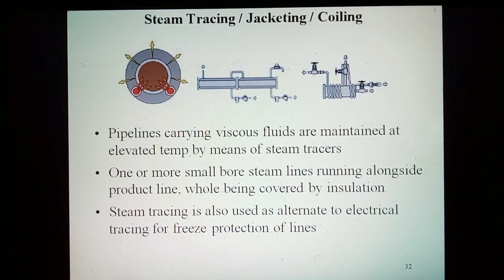Steam tracing. Pipelines carrying viscous fluids are frequently maintained at an elevated operating temperature by means of steam tracers. These usually consist of one or more small bore steam lines running alongside the product line, the whole being covered in insulation. Steam tracing is also used as an alternative to electrical tracing in freeze protection.